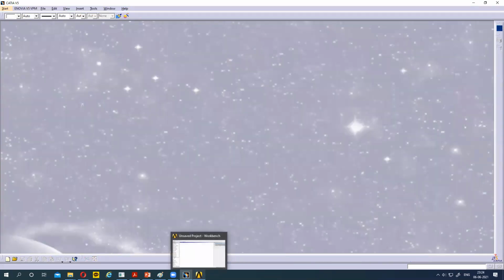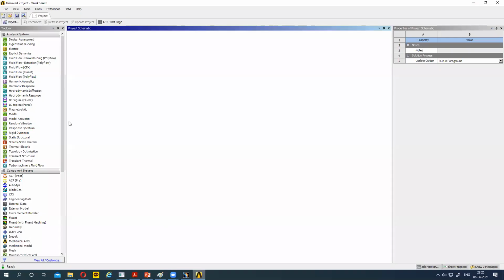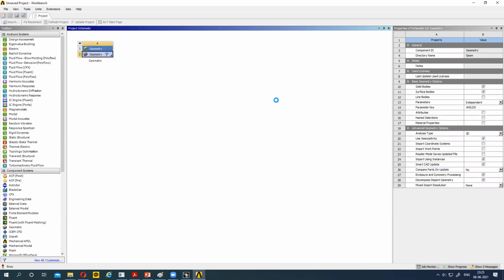The same thing we can do in ANSYS also. In the same way, in ANSYS just create points and use a line. Here, design modeler, ANSYS geometry. I am going to work with design modeler. The analysis type is 3D here, not 2D. 2D is only for plane stress and plane strain analysis.